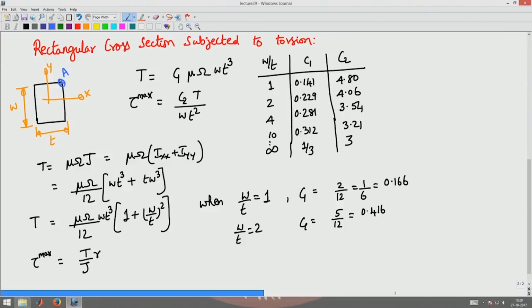There is no continuous flow of shear stress in this section, because point A has to have 0 shear stress. Why should the point A have 0 shear stress? It is because there is no complementary shear applied on the respective top and side planes; in this cross section there is no shear stress applied here nor here.